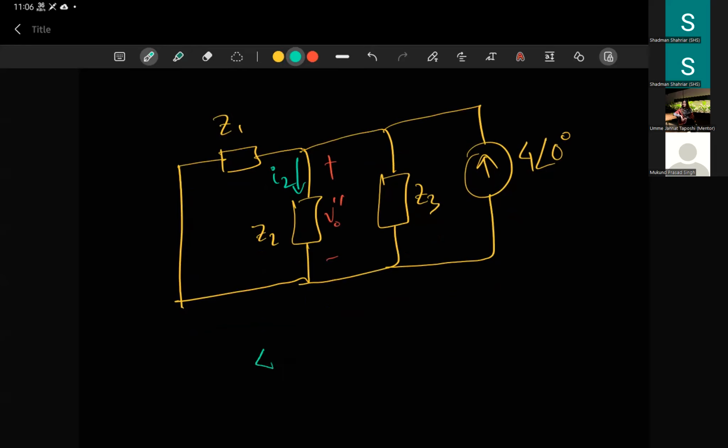So remember how in voltage divider rules, if we had some voltage like 30 volts times all the resistors like 3 plus 6, and we want the voltage across one resistor, say the 3 ohm resistor, this is how we write it. For current divider rule, for example, we have 4 angle 0 degrees here. The value of I2 will be to divide this 4 amperes into all these resistors.